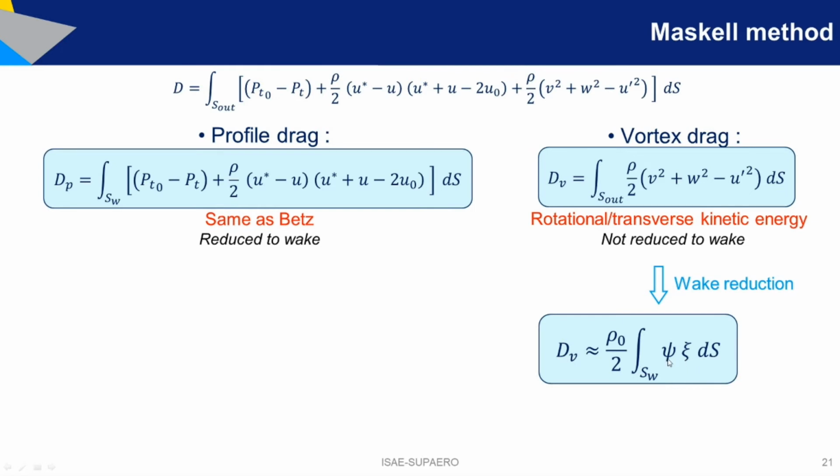But what's the meaning of these terms here? Well, this term is the axial vorticity. It's basically the rotational of the flow field along the aerodynamic x-axis. This is related to the lift generation, or basically in a lifting line environment, it's the filaments shed by the wing lifting line. So the same vortices that have generated lift are shed downstream and generate vortex drag. So it's clear this expression if you do the link with a lifting line.